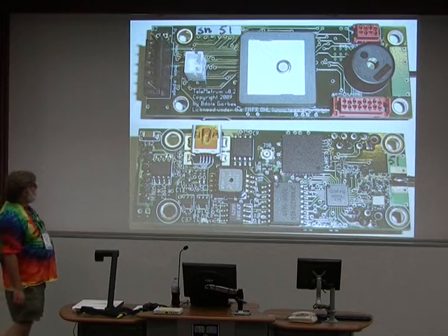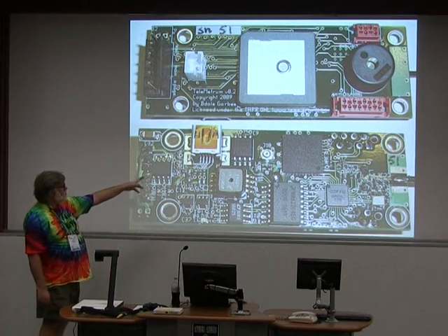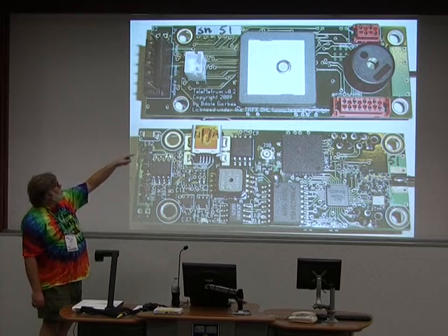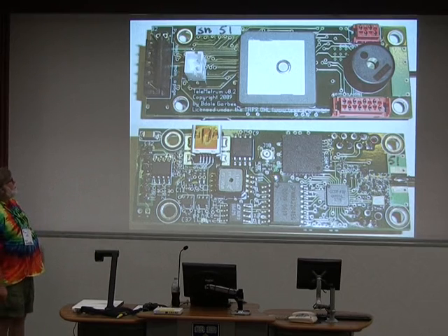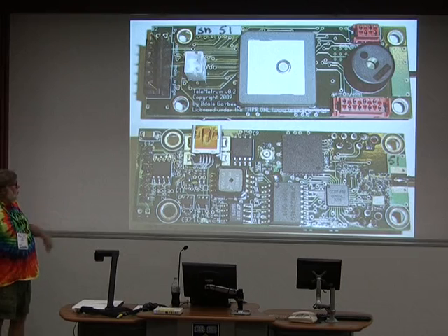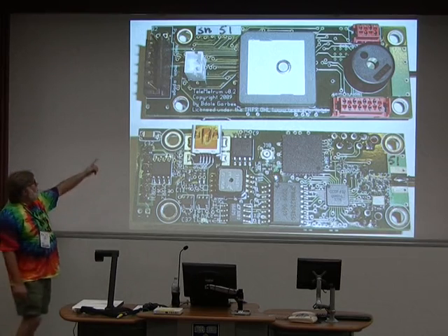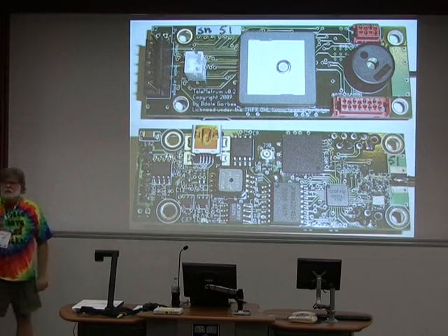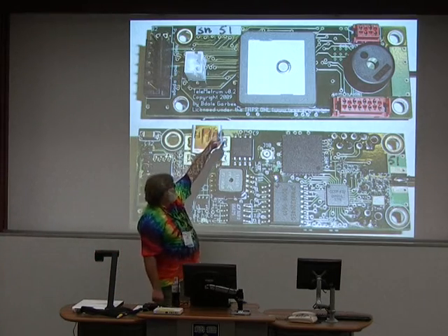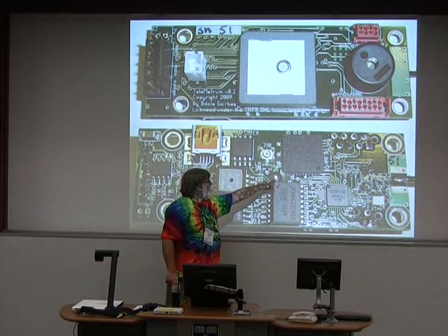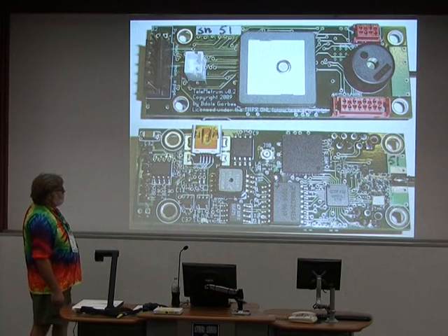But what I realized here was that with all the extra parts I needed to stick in to put the GPS in, putting all of the surface mount parts on one side of the board and putting the through-hole parts in from the other side of the board, which I think I actually have to give Keith credit for thinking that idea up, meant that I could still hand load the board at home and reflow it in my electric skillet, and then hand load the through-hole parts from the other side. We got the area advantage of the big GPS patch antenna. This is the only impact on this side of the board, where the center pin gets soldered through, and it was a much more efficient use of space.